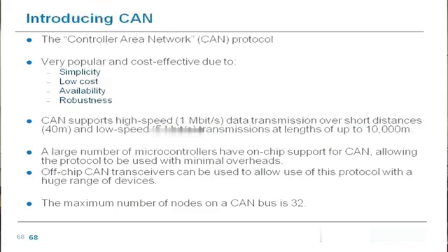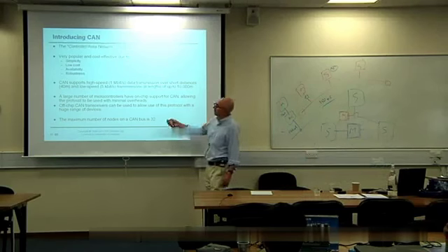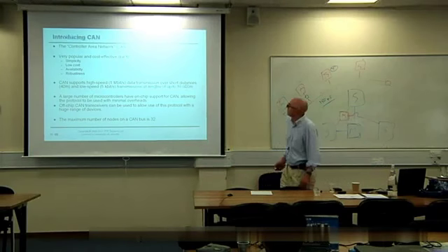Briefly, one of the ways that you can schedule these systems and the way that many systems are put together is with the controller area network protocol. Simple, low cost, high availability, pretty robust. 1 megabit per second data transfer rate. More recent protocols again have about 10 megabits per second. That's a good thing, but they haven't really taken off because the data transfer rates mean that you actually need quite powerful processors to keep up with the data transfers, etc. And that has a cost. CAN remains very, very popular, and this has proved to be fast enough for many applications.